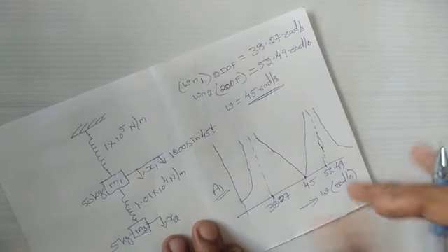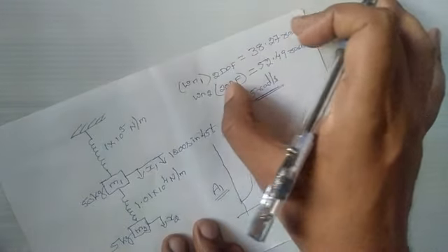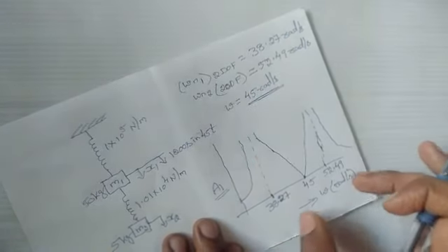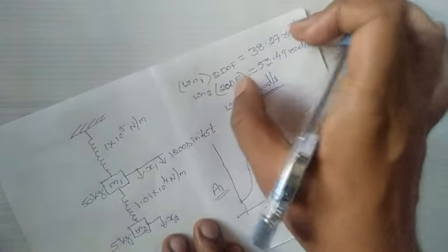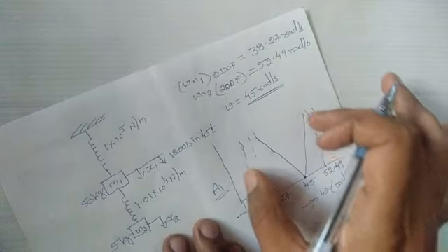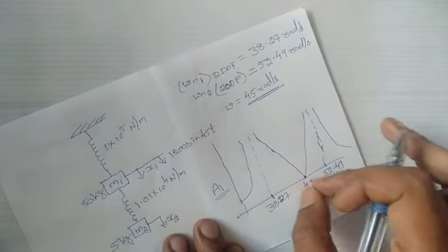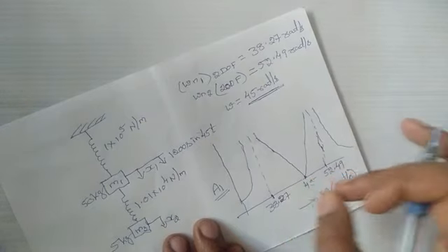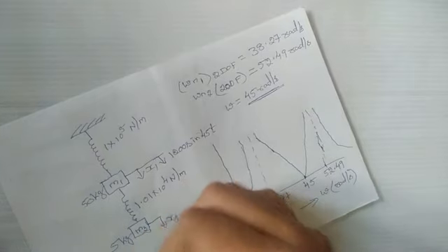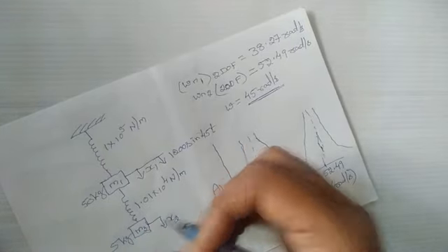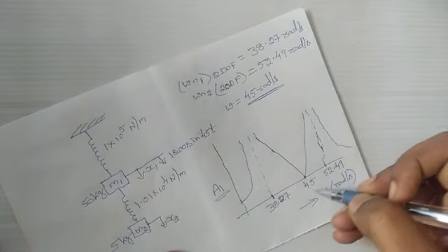These two are the natural frequencies of the 2 degrees of freedom system, and when the forced frequency matches the natural frequency, it is going to resonate, but only at 45 radians per second the amplitude is going to be 0, because this absorber is going to absorb the vibrations of this machine at 45 radians per second.